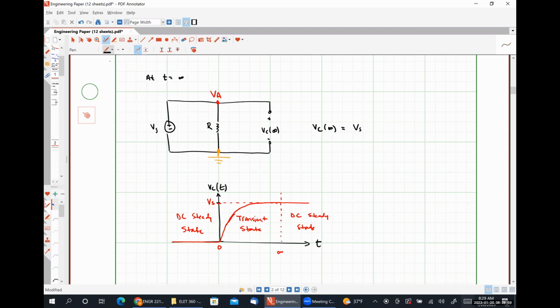So mathematically, this DC steady state at the end is our forced response, okay? So this is what the forcing function is making the energy storage element do. It's making it have a voltage of Vs at t equal to infinity because it's still connected to the circuit. So we are going to call this quantity simply y at infinity, okay?